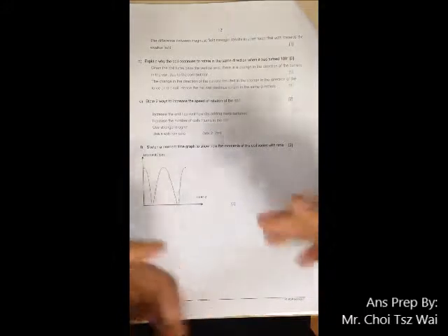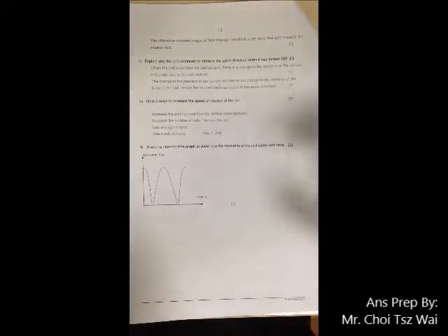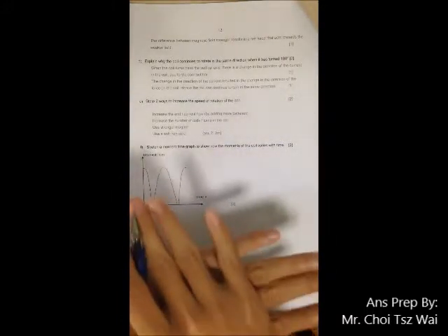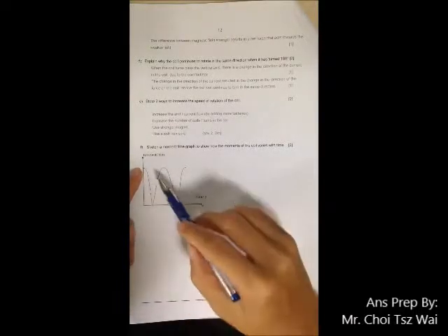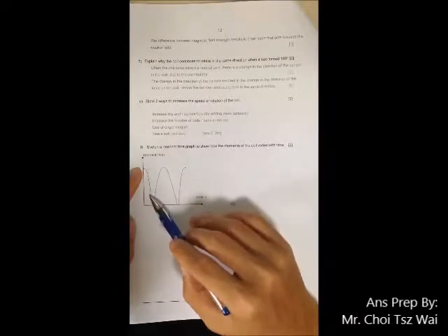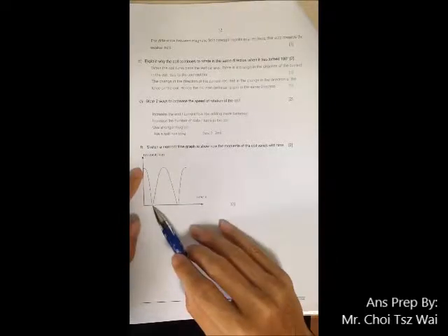The magnetic field from the coil and the magnetic field from the permanent magnet will have the greatest overlap area when the coil is sitting flat. So that's why you will have the greatest moment here, and as it starts turning, there will be less overlap, and so the moment will decrease. Okay, and then what happens? Why does it reach zero?